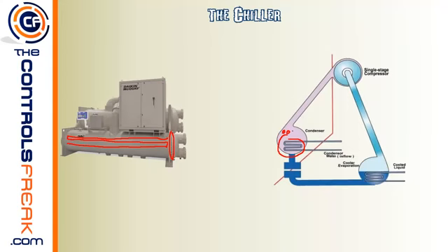I've seen some chiller barrels that had literally 100 or more tubes inside the chiller barrel. So there are tiny little tubes all throughout this chiller barrel, and that's where you get the water running back and forth through this barrel to do the heat transfer. So just a little bit of extra on the chiller. Let's move on to the next step.